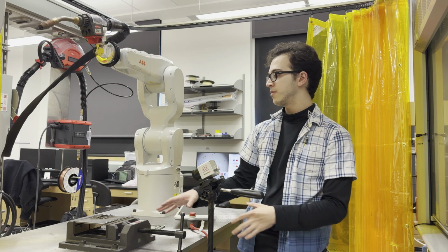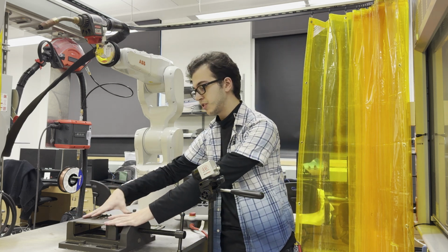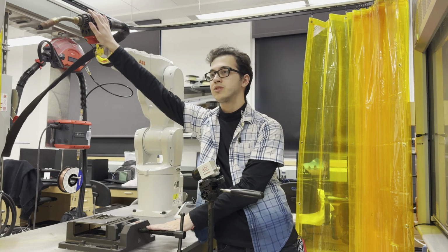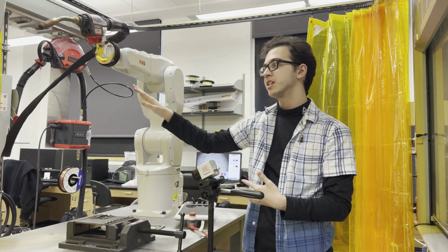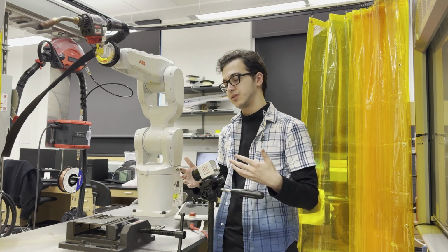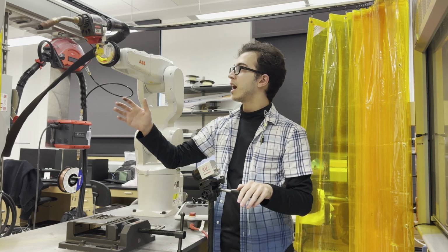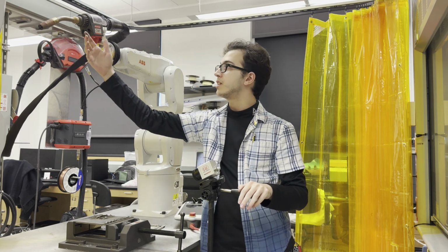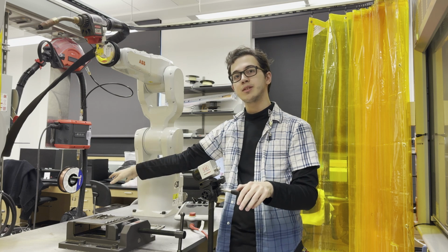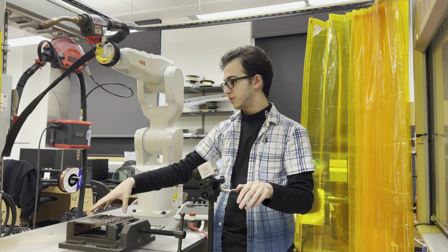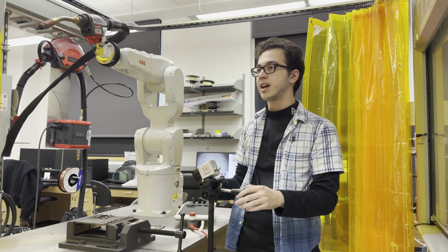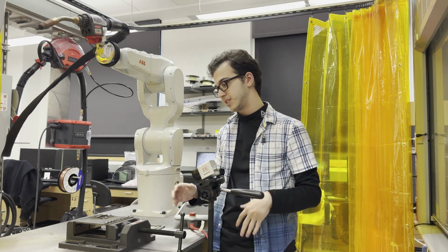So we have our testing area, our steel plate where we create welds. We have our CMT welder. CMT stands for cold metal transfer. It is a process of heating metal deposition similar to that of MIG. So we have carbon steel wire feeding through a tube with an electrical current running through it, and it is shielded by argon gas to ensure the safety of the operators around. There you'll see welding curtains, and we normally wear welding helmets in the vicinity.